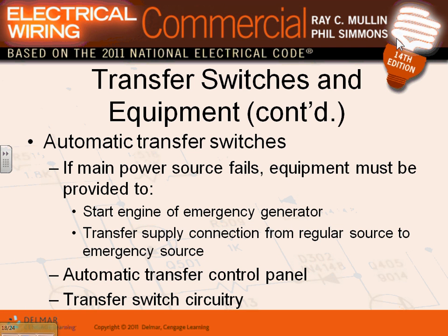Auto transfer switches. The auto transfer switch, guys, remember when Jay was here, the job of the auto is to sense that the power is lost first, and then close the contact to start the generator. And when the generator comes up to speed and energizes this side, it flips the whole building or part of the load to this side. Really, that's the job of the emergency system. Start the engine, transfer. A lot of people forget that little function here.